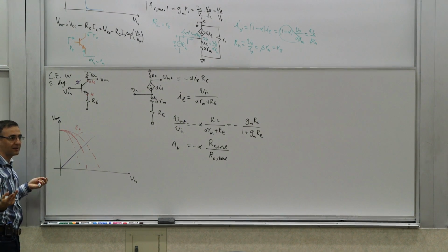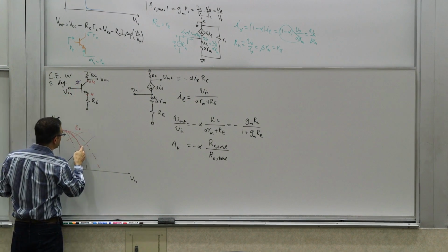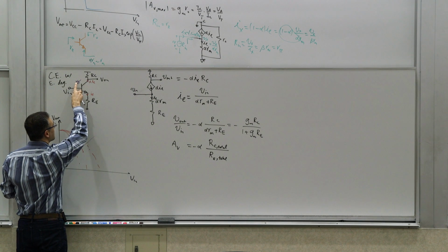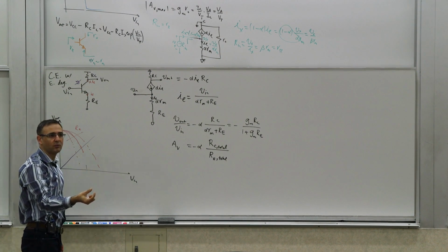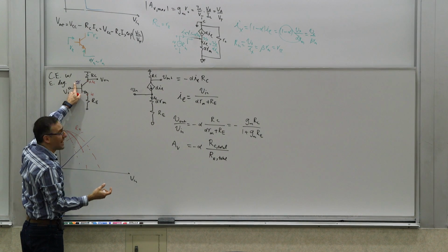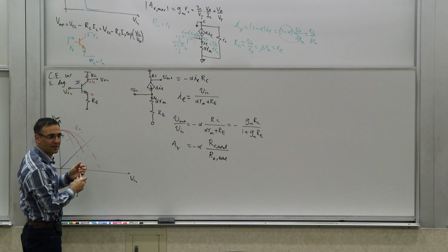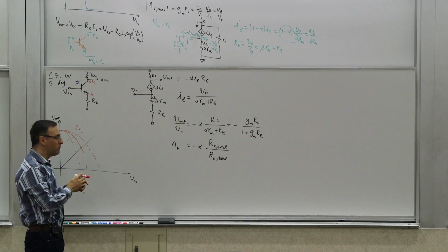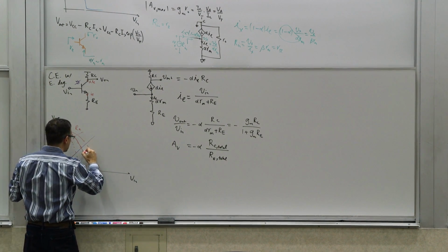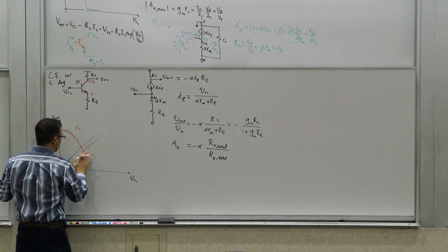There are two ways to think about that. Let's think about it as a diode. Now, as I increase V in, now this diode is forward biased, so its voltage is going to remain 0.5, 0.6, whatever, right? 0.7. So this voltage is going to track this voltage with a 0.7 volt or 0.6 volt difference. So it's going to be 0.6 volts below that. So this is going to now start tracking it up. So let's keep one of these curves to avoid confusion.